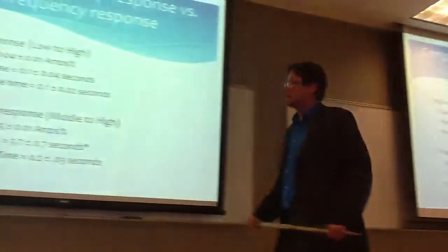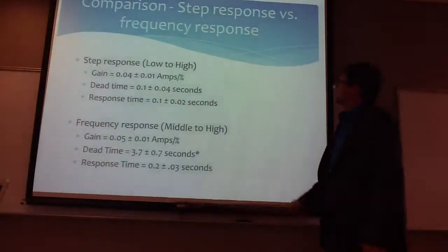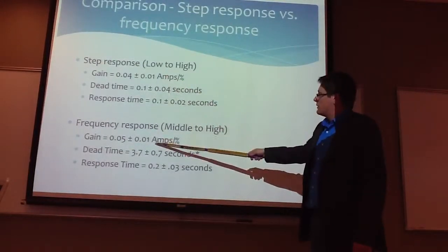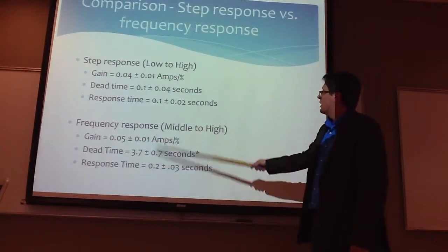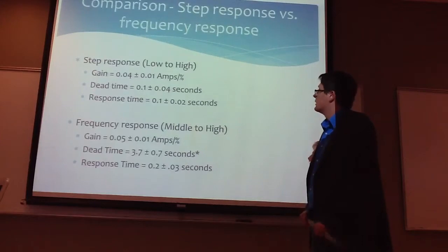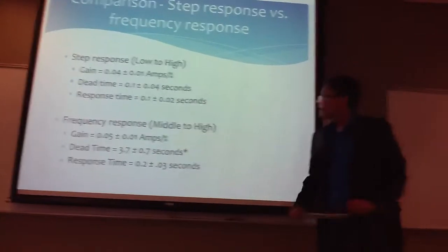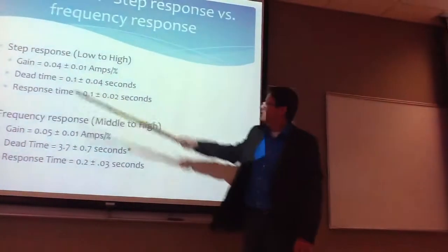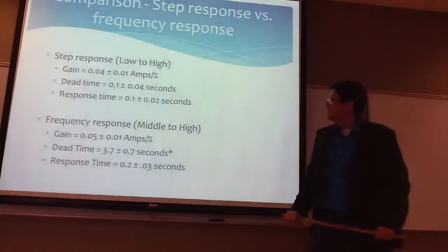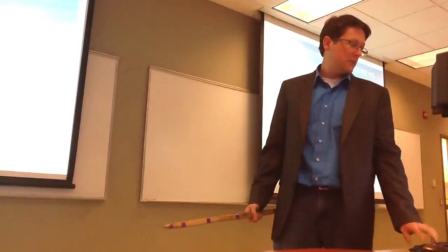Comparing the step response to our frequency response. Again, our gains correlate pretty well, response time, and then our dead time, again, was 0.03 that was calculated. So there's a little bit of variance in the dead time when we compare step response to frequency response.